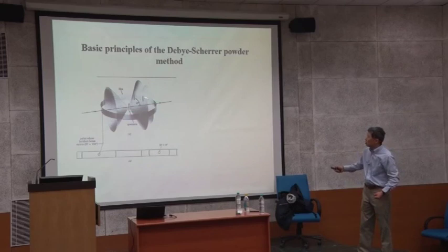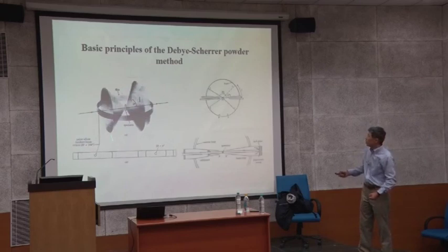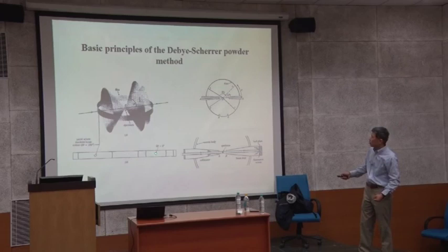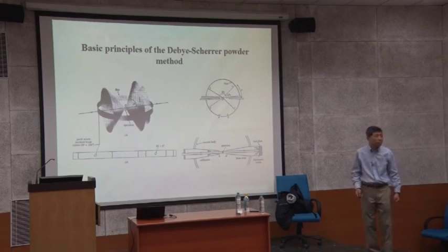But usually your X-ray diffraction is scanned along that direction. That's why you see a peak here in that direction. First peak and second peak are touching each other. Okay? So that's a Debye-Scherrer camera, and then basically you see the shadow of the cone, one cone, second cone, and then the next cone. But this X-ray diffractometer, basically, it is a theta, two theta direction. So you can see that single peak, next peak.